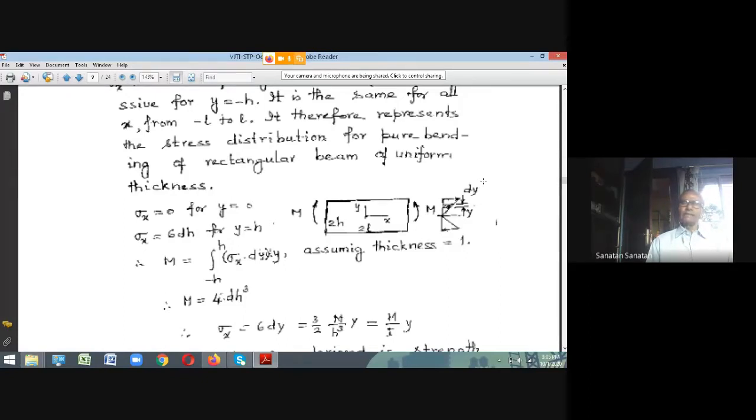Any form of that stress function is going to satisfy the equilibrium equations, and the constants involved you have to decide by seeing that the boundary loading is satisfied. Any form of the phi function, irrespective of its form, satisfies the two equilibrium equations because of the definition itself.